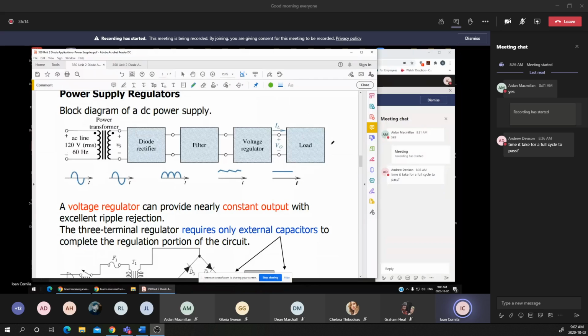You notice that any of the chargers or any of the AC to DC adapters will always have a maximum current. If the current is higher than the maximum current, usually they have an internal protection that will short circuit, actually it will cut off the voltage on the output.